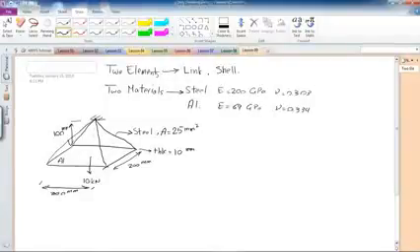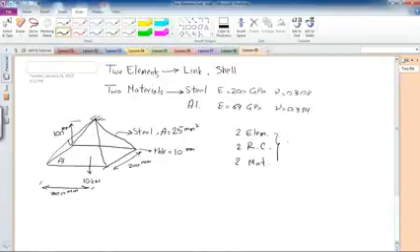And as you know, each of them has different cross-section or real constants, so I have to define two elements, two real constants, and two materials for this analysis. And how I define these is when I'm about to do the meshing, as you will see in the example. So with this, let's go to ANSYS and do the analysis.